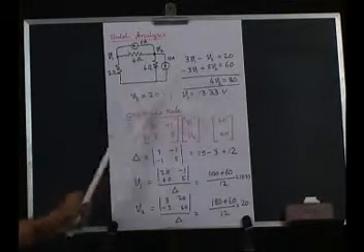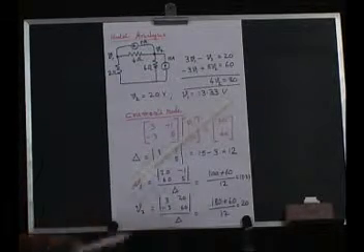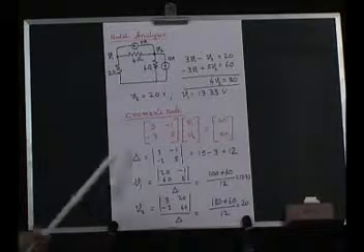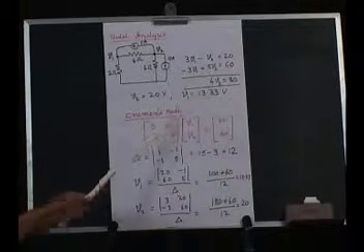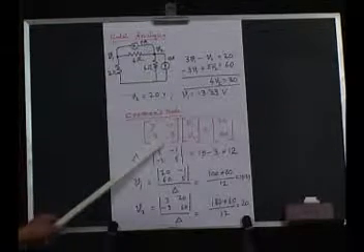So, we find V2 first, this is 20 volts. Therefore, V1 will become 13.33 volts. This is one method, the elimination method. The second method is Cramer's rule. What we do is, we represent these two equations in matrix form.